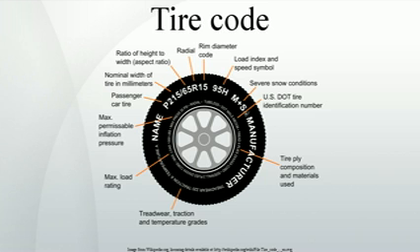See table below. Some light truck tires are approved for dual use, that is they can be run in pairs next to each other. If so, separate load indexes will be specified for single and dual usage. In the example shown in the light truck tire illustration, the tire has a load index of 114 if used as a single tire, and a load rating of 111 if used in a dual pair. Tires without this designation for dual usage are unsafe to use as such. A 1 or 2-digit letter combo, speed rating. See table below. Additional marks, see subheading below.